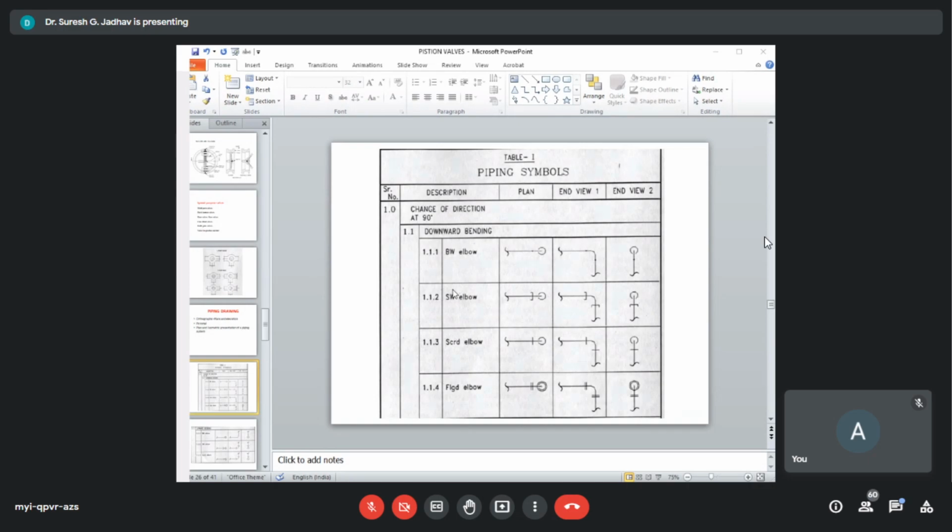Might be you drew the title blocks at the bottom on the right hand side, and you wrote name, seat numbers, roll numbers, and you used different kinds of symbols, first angle symbol, third angle symbol, whatever symbols or methods are available in engineering drawings or graphics. So likewise, the dimensional details of the title blocks are specified under IS 11665.